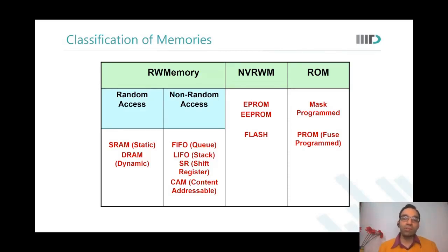Yeah, but fuse programming, you do inside the fab itself. EPROM you can do at the customer end. Okay, so like in this mask program, the instructions that we need, for example, boot sequence, they are fabricated at the fab itself. Similar is it for this PROM also? No. PROM will not store instructions. PROM will only store calibration data.